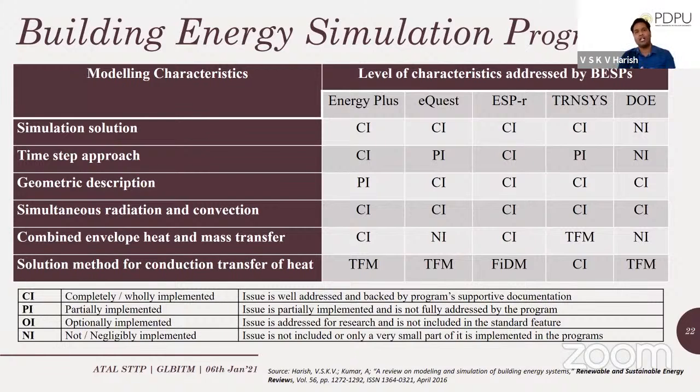For example, I developed the model through equations and then converted it into transfer equations and then state space equations in MATLAB, and validated it through intra-model validation, a comparison with EnergyPlus. Same set of inputs, same model in EnergyPlus, compared both the outputs. Also compared this with already published articles, the outputs coming from them, and that's how the validation happened, right? So not only the empirical validation, but the intra-model comparison validation also happened like this. So among the building energy simulation programs, because I had that purpose, I used EnergyPlus. Depending upon the different purpose you want to use it for, you can use different energy simulation programs, which you are seeing on your screen.